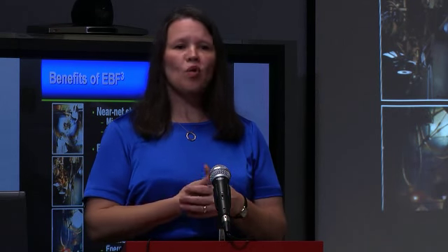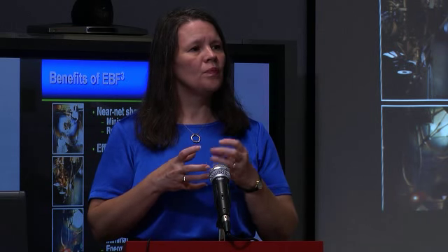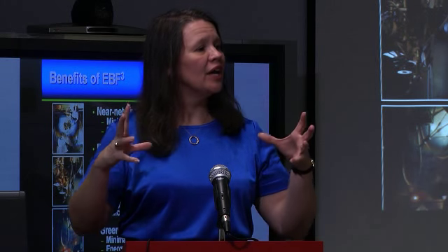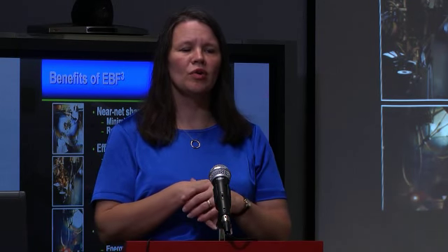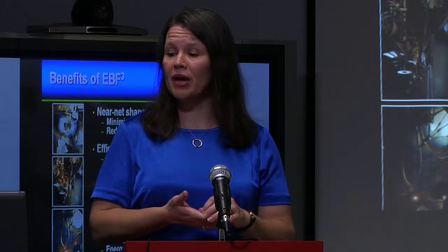So some of the benefits, one of the reasons that you want to do this is it allows you to build a component near net shape, which means that instead of starting with a big block of material and machining it down to your final part, you end up just putting the metal where you need it. It's very similar to if you've heard of rapid prototyping, stereolithography. Some of you that may be working with some engineering groups may have heard of some of those technologies. Very similar. A lot of different technologies are building up in plastic. We're building up in metal.